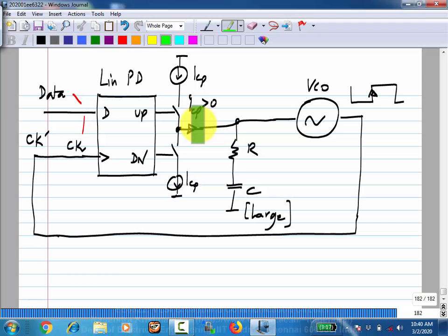If frequencies are different, what happens is that slowly there will be charge accumulated on the capacitor, and eventually the voltage across the capacitor should be such that the voltage shift will cause the appropriate frequency shift. Okay. So essentially I will call this VC from here on, the voltage across the capacitor. The role of VC is to move the VCO frequency to the right value. And the role of VR is to provide instantaneous phase corrections.